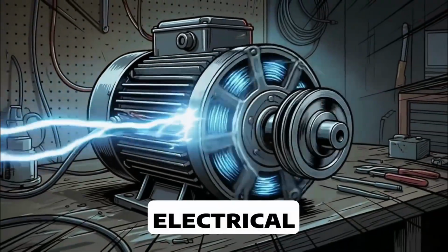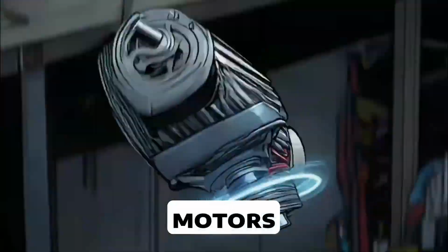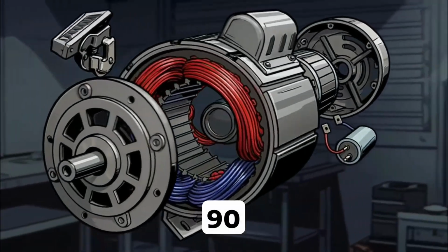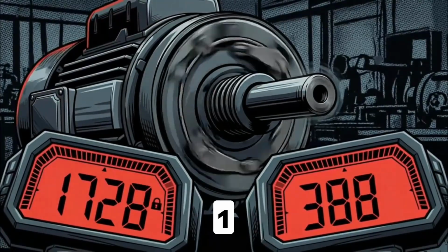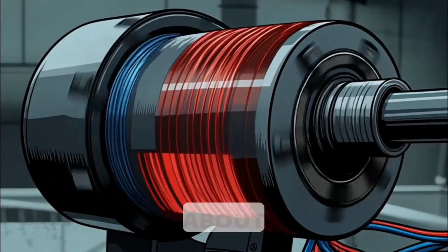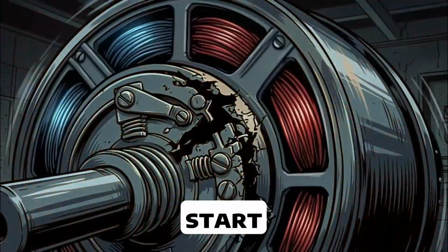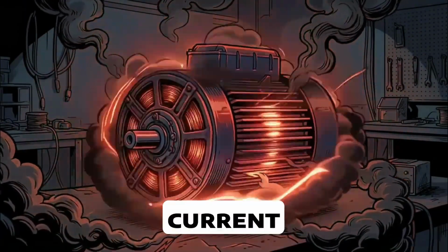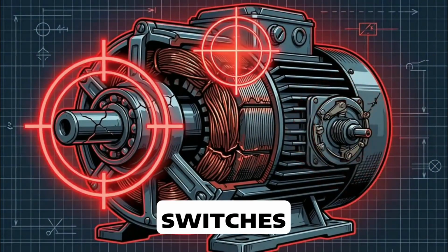Motors convert electrical energy into motion using magnetism. Split-phase motors use start and run windings separated by 45 degrees to 90 degrees. Common speeds are 1,725 and 3,450 revolutions per minute. At about 75% speed, a centrifugal switch opens the start winding. Failed switches can cause humming, overheating, or high current. Main trouble spots are bearings, windings, and switches.